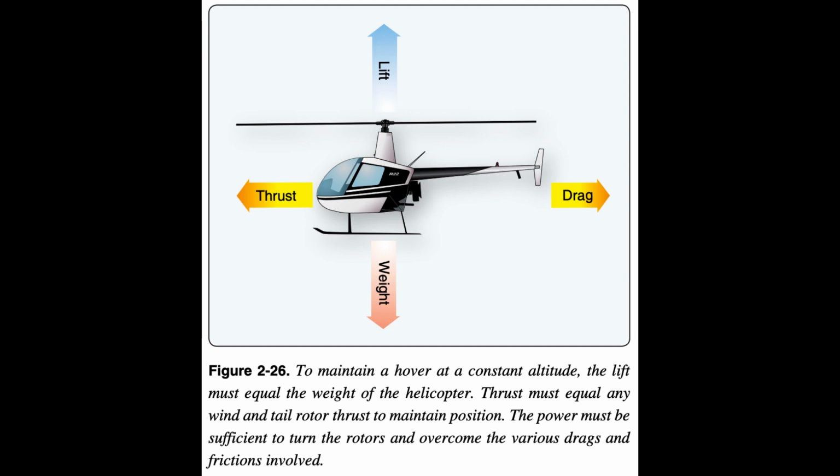Figure 2.26. While hovering, the amount of main rotor thrust can be adjusted to maintain the desired hovering height. This is done by changing the angle of incidence, by moving the collective of the rotor blades, and hence their AOA. Changing the AOA changes the drag on the rotor blades, and the power delivered by the engine must change as well to keep the rotor speed constant.